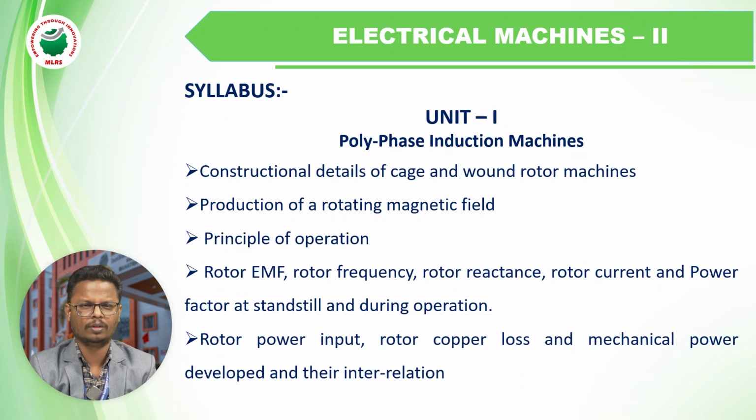field. How the rotating magnetic field is produced, what conditions are required, mathematical proofs, etc., and the principle of operation. The three-phase induction motor is a self-starting motor, and the single-phase induction motor is a non-self-starting motor. How the three-phase induction motor self-starts, and why the single-phase induction motor is not self-starting, will be discussed in the principle of operation.